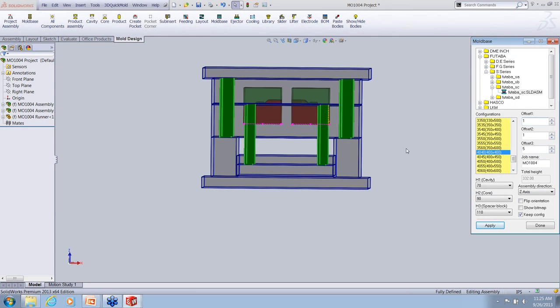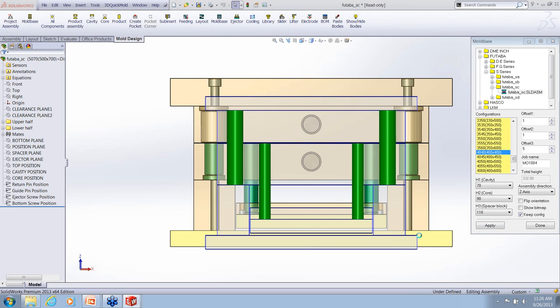Also, for the direction of the mold you want to place, you can directly view the orientation here to place the mold base in this assembly. So I'm just going to check all the information here, provide these parameters, and continue. I'm going to apply this. Now you can view here that the complete mold base will be added to the same assembly. Once again it will pop up asking whether you want to change or go with the same mold base. It will take some time, and then it's going to cover the complete assembly.